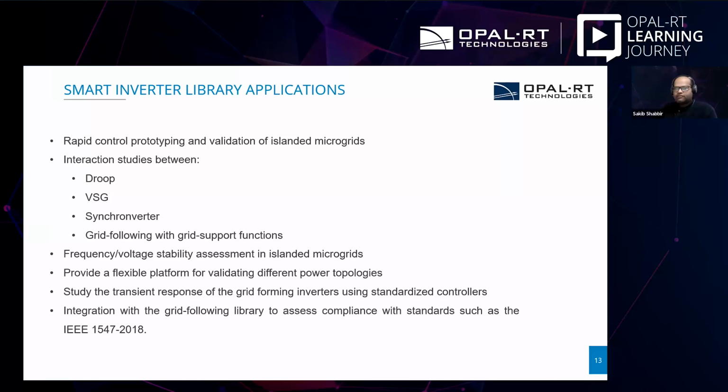We can also use it for transient stability analysis, and most importantly, we can use it for integration with the grid following library to assess compliance with different standards, available as safety functions or different programmable grid support functions in the grid following library that was developed according to the IEEE 1547 standard.